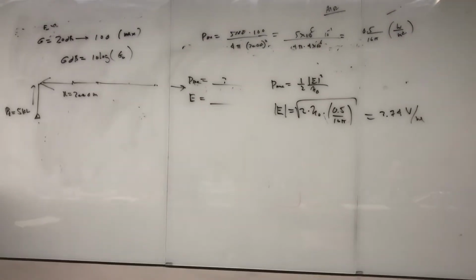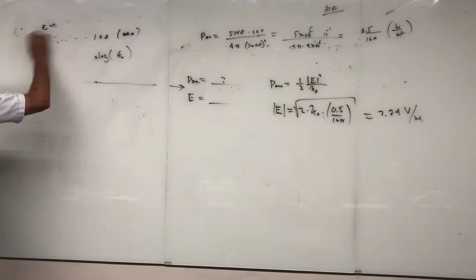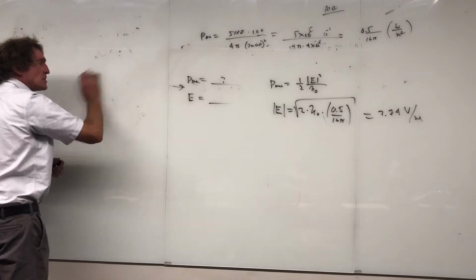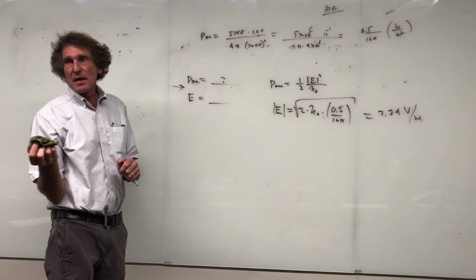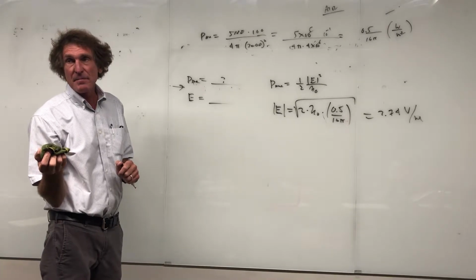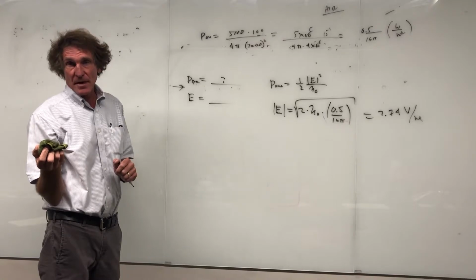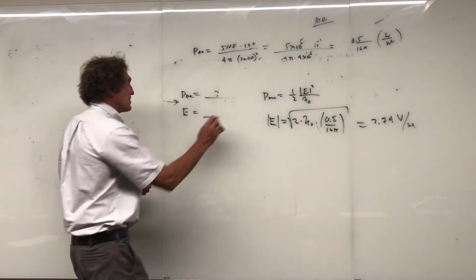Now, after that example, we get back to what I was up to. And you know, when you buy antennas, any type of antenna, the gain is always in dB. It'll be dB iso usually. It means compared to an isotropic radiator, but it's always going to be in dB.